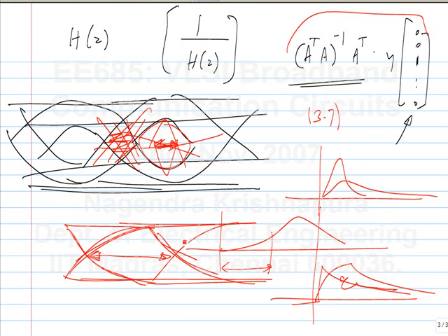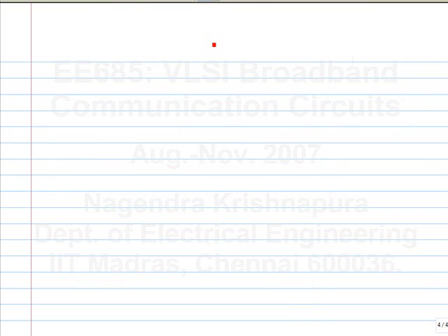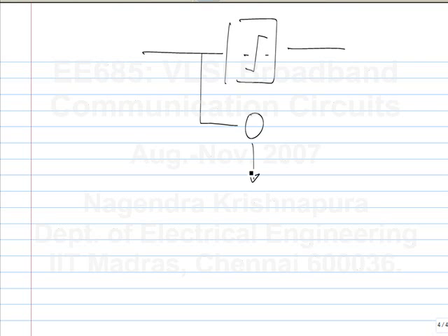No, there is one assumption, right? There is also one particular assumption that I had mentioned once. You make the decision, and you say that this error is the difference between the decision you made and the input you get. Okay? But the actual error should be the difference between this and what you sent. That is the actual error. Now this is an estimate of the error. If this is wrong for too many cases, adaptation can be driven in the wrong way. Okay?